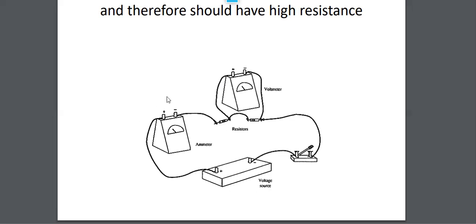Almost no voltage would drop across this ammeter. Why? Think about the essential question: because it has really low resistance. V equals IR, that's the voltage drop. V equals IR, Ohm's law. This thing has very, very low resistance. Its R is very, very low, close to 0. It's designed to have low resistance so that it's not going to have much of a voltage drop across it. It just lets the current flow through, almost 0 resistance, and so almost 0 volts drop.